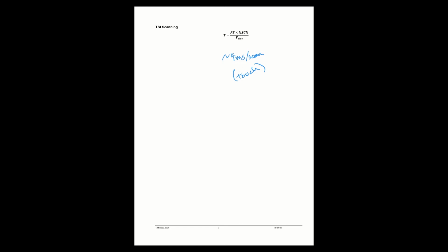It's 4 milliseconds, and it's when we're touching the electrode. Well, when we think about our time slice scheduler, 4 milliseconds is a significant amount of time, right? If we had a time slice period of 10 milliseconds, that's 40% of our CPU load right there.